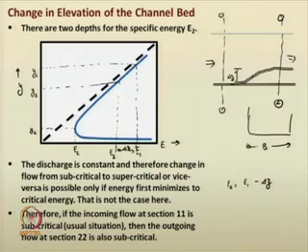Definitely in normal practice, due to the rise in bed level, there will be a change in the flow pattern, but you know that the specific energy at section 2 is less than the specific energy at section 1 by a magnitude del Z. So, use this diagram, for the corresponding E2, to select the subcritical flow depth Y2.